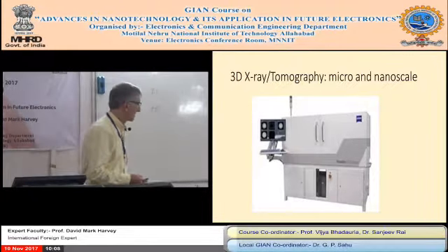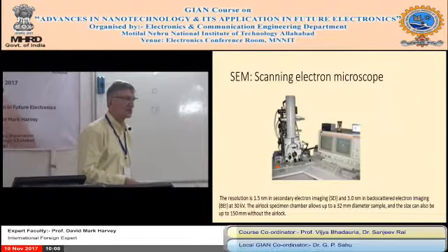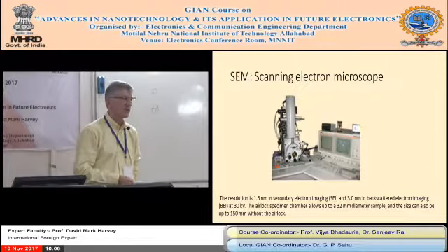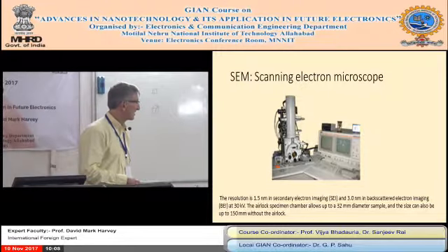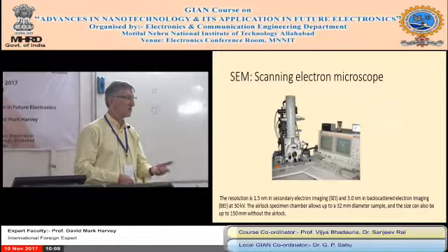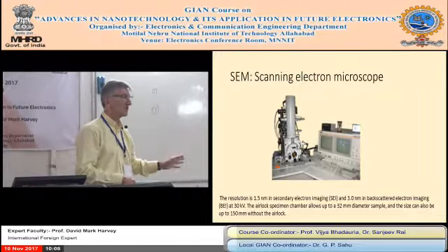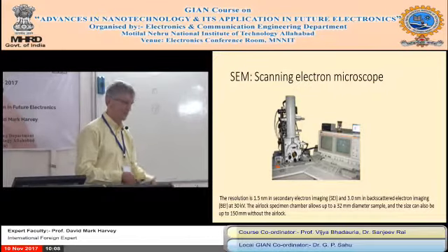Standard, this is just a picture I found, but the scanning electron microscope has been used for many years. It's got very high accuracy, as you can see there, in the nanometer range, for looking at any objects, using biology, engineering, and so on. Most universities and most companies now doing validation will have one of these, or maybe two, because you can not just look at the microscope side, you can look at the materials by introducing X-ray analysis into these things. And again, they're not so easy to use. You need an experienced operator or a technician to help you.